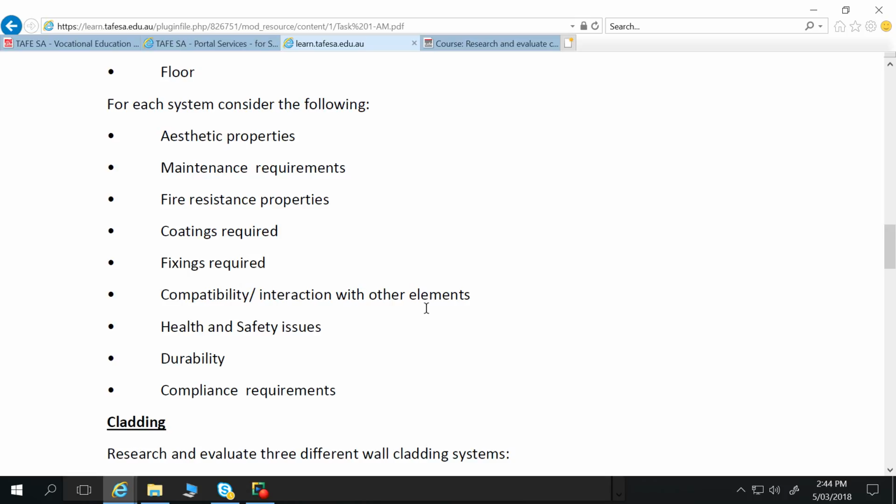with the various manufacturers of your aluminium sandwich panel cladding, they're not going to want to talk about that. In their initial product literature, they will say it is fire resistant, which it is. It is fire resistant up until a point, up until you really get it going. Once you get it going, then it keeps continuing.